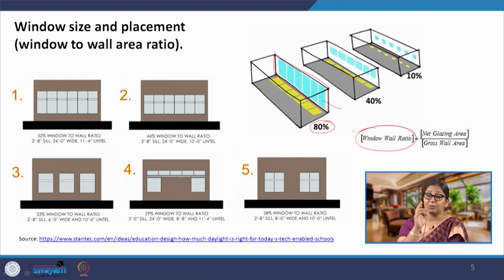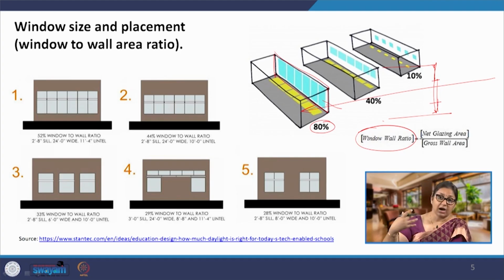East and west will allow us to bring in direct sunlight, also in the deeper areas, because the altitude of the sun is very low, and when we have a window which is facing east, we are going to have a much deeper penetration. Of course, we have to clearly see that the light has a limited range, a limited reach. If we provide a window in the east, we cannot expect that it will still travel some 100 feet inside the building. No, it will not. It will still have the limitation which we have just seen.